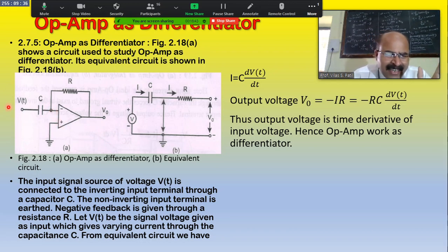Okay, this circuit is very simple. An RC factor is used. We know that if a resistance and capacitor are connected in series, that circuit is known as a time constant circuit, because the voltage amplitude across the capacitor depends upon e raised to minus t divided by RC. That is an exponential quantity: the voltage across the capacitor changes exponentially with respect to time with the ratio minus t divided by R into C, where R and C are the magnitudes of the resistance and capacitor respectively.